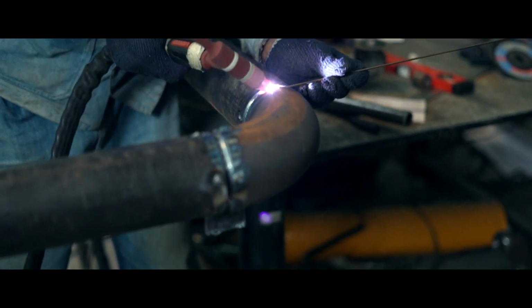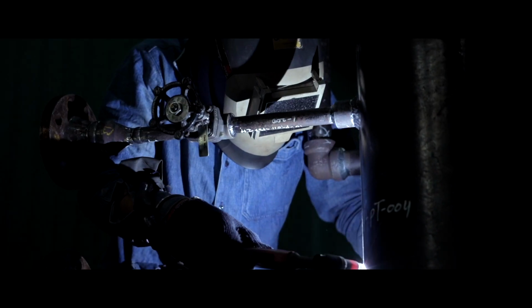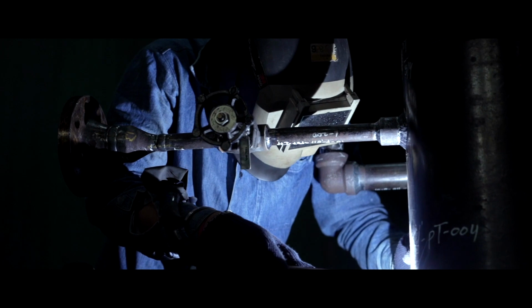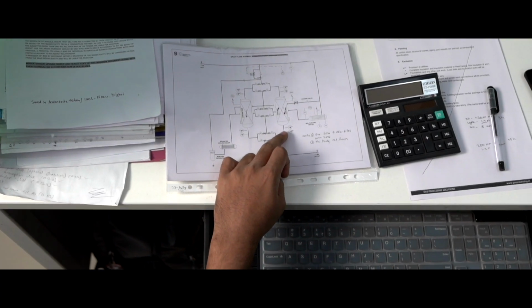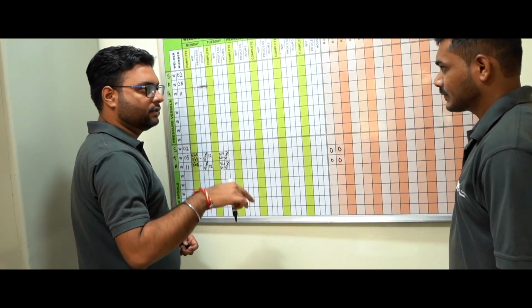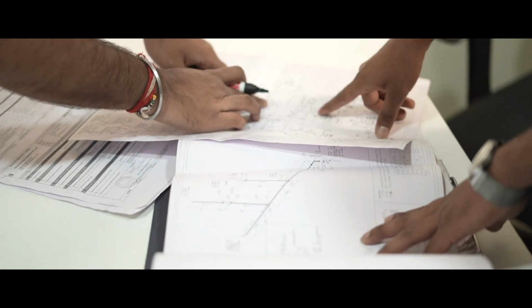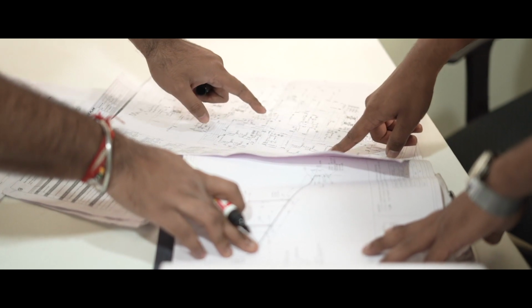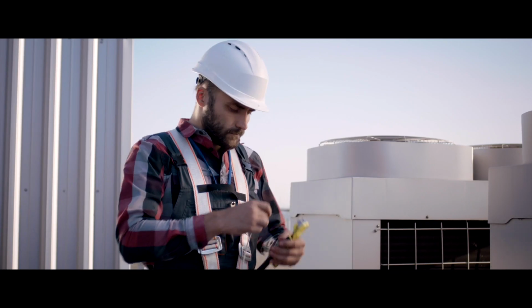We are providing 100% full penetration joints without back chipping to ensure 100% RT. We are doing FCAW, GTAW, SMAW welding processes as per ASME Section 9 and approved WPQ, PQR and WPS. We always track the record of these weld joints through our welder performance list, and we track on a daily basis how many weld joints are completed.